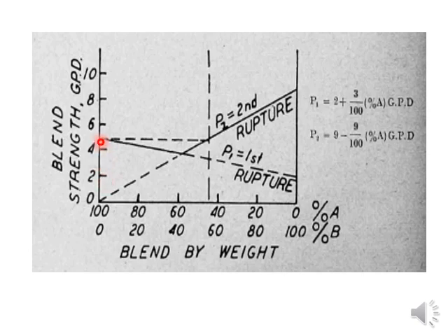We achieve 5 when we use 100% of fiber A and no fiber B. So only by using fiber A we are getting 5. But as we increase the blend of fiber B up to around 40%, there is no advantage in terms of increase in tenacity. Although fiber B has higher tenacity, we are not getting any advantage.